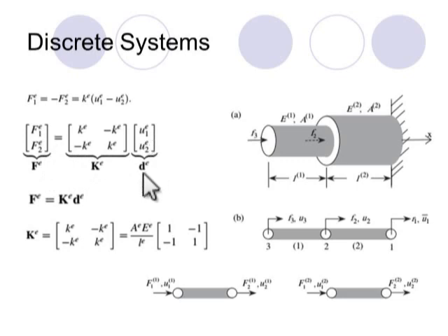Here D is the column vector of the displacement, F, which is written in bold letter, is the column vector of the force, and then I have the stiffness matrix. Here capital K is the stiffness matrix, the elemental stiffness matrix. Certainly it has elements of stiffness of the truss element, ke, minus ke, minus ke, and ke.